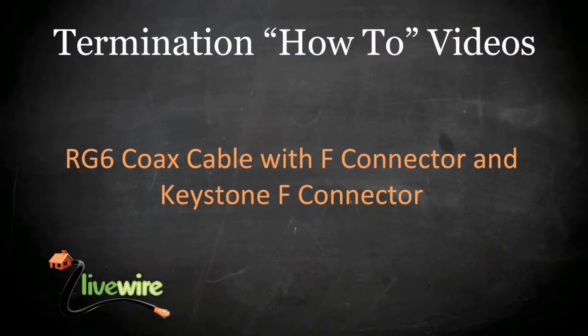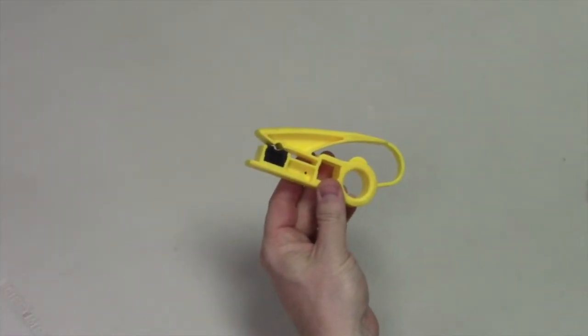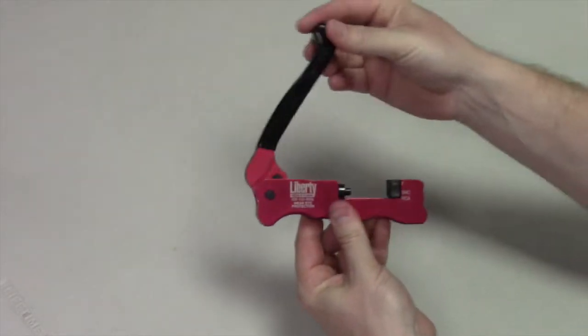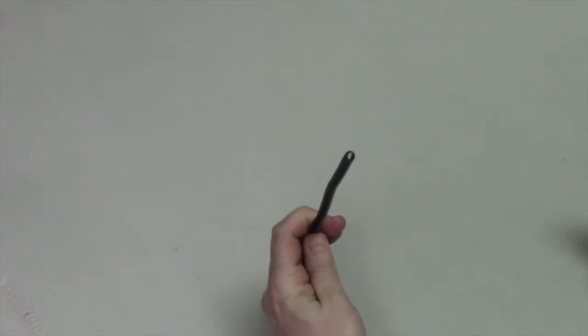Now we're going to learn how to terminate an RG6 coax cable with an F connector and a Keystone F connector. Remember, the RG6 coax cable is mostly used for cable television. You will need a pair of coax strippers, as well as a coax compression tool. And of course, you need the RG6 coax cable.